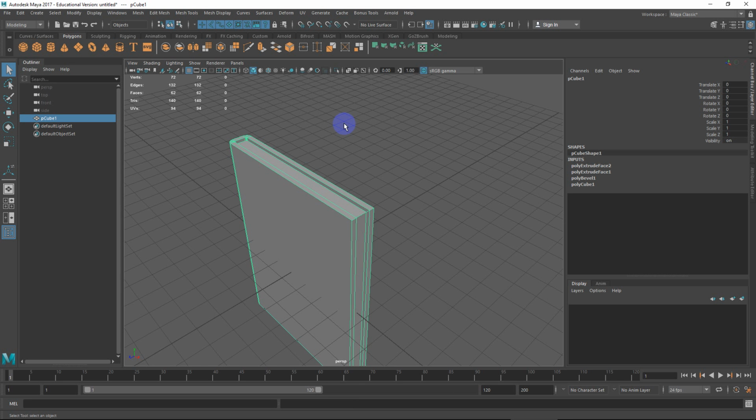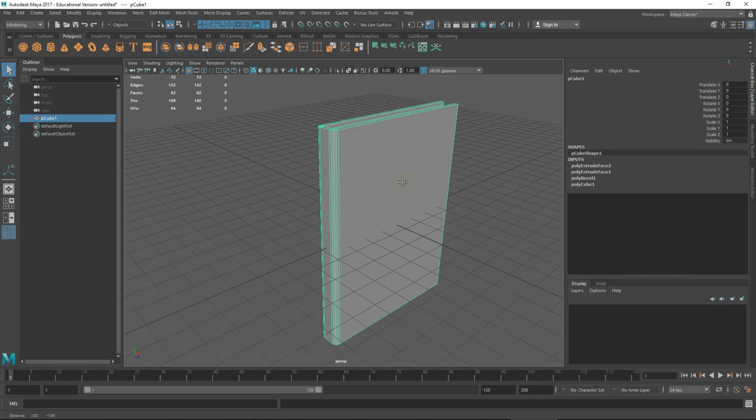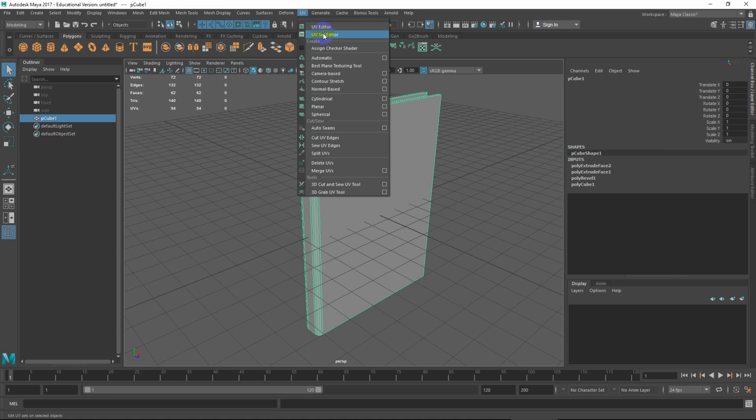Before you mass duplicate things, before you merge stuff into a scene, you do want to try to unwrap every piece that you have. So in some cases, if you do have one prop and it's got multiple little rivets, bolts, whatever it might be, you can easily delete those, unwrap the one piece, and reduplicate it again, right? Redo a duplicate special, redo that stuff so it carries the unwrap with it. In this case, I'm just taking a book and unwrapping it before I duplicate in the scene.